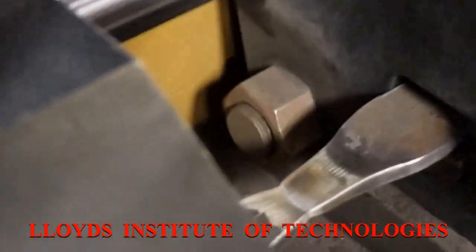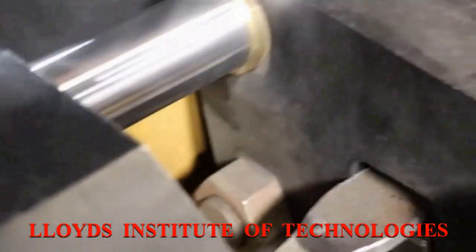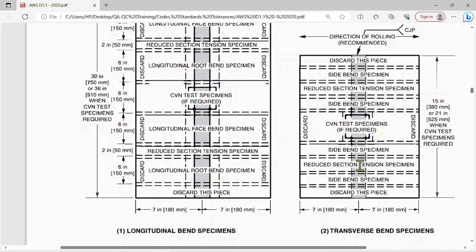Okay, and if you have to go for CVN testing, that is, if required and if mentioned in the contract, only then you will have to go for that. So currently, let us not consider that. In that case, your length will be a minimum of 15 inches, that is around 380 millimeter minimum.